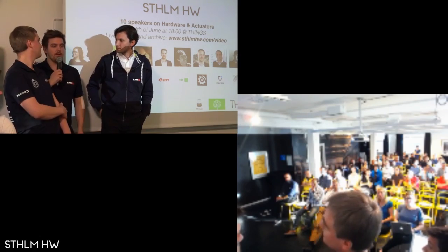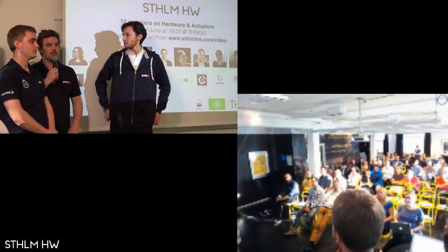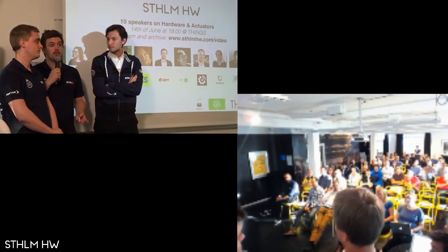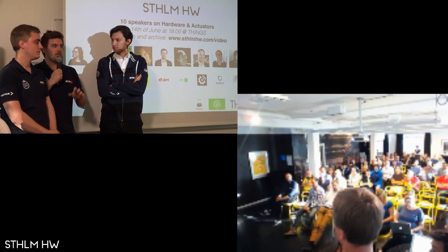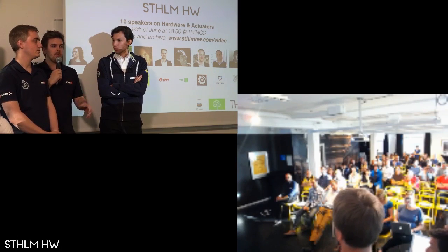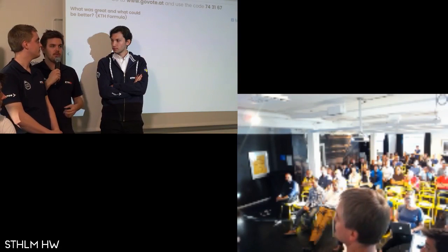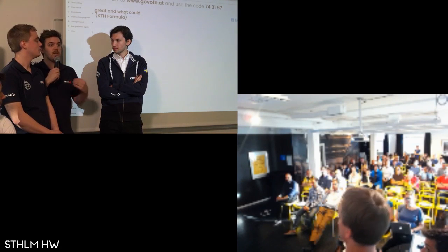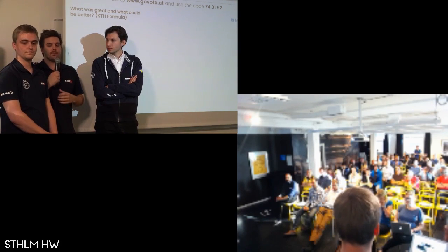Yes, what kind of communication is used in the car? It's CAN bus everywhere, basically. We have two buses, one from the main controller to the inverters, so we have that isolated from the rest of the system. And then all of the sensor boards that collect data from the sensors send communication over the CAN bus to the main controller as well, over one bus.